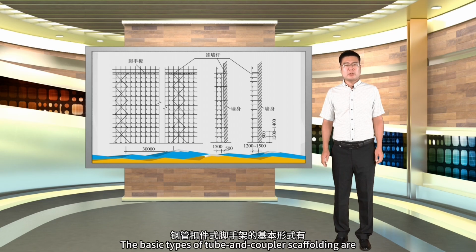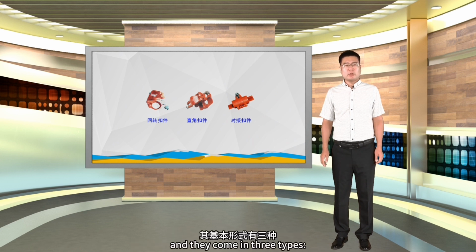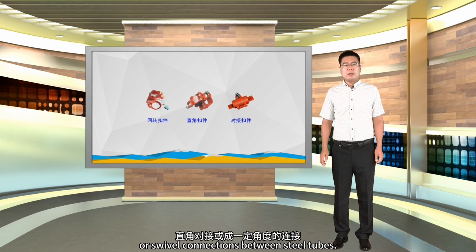The basic types of tube and coupler scaffolding are single row and double row scaffolding. Couplers are connectors between steel pipes, and they come in three types: right-angle couplers, sleeve couplers, and swivel couplers. They are used for right-angle, inline, or swivel connections between steel tubes.